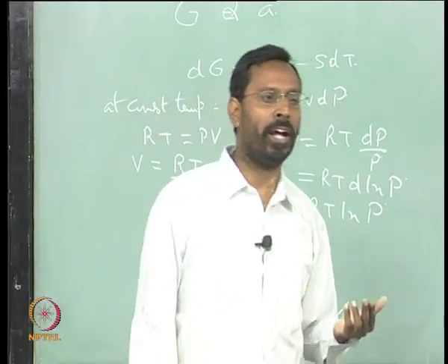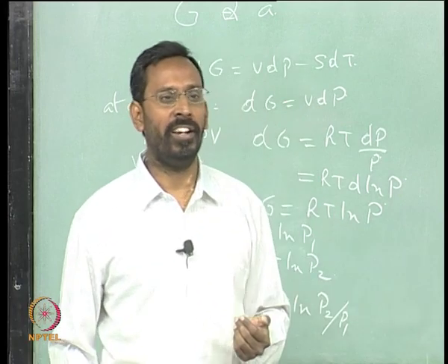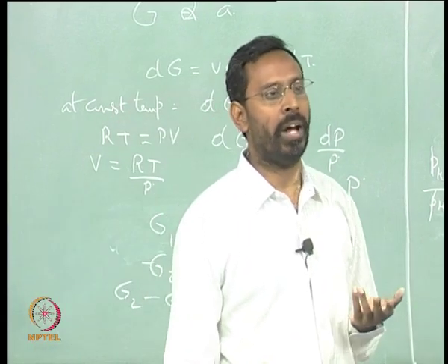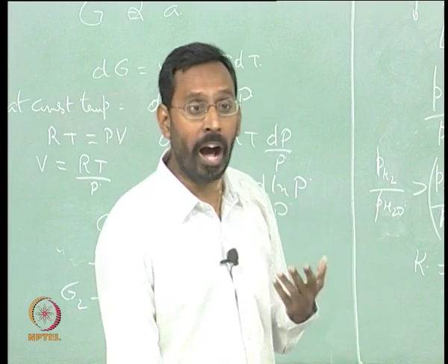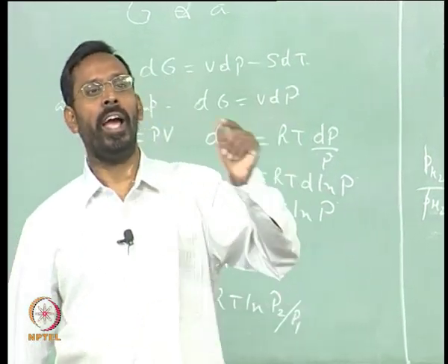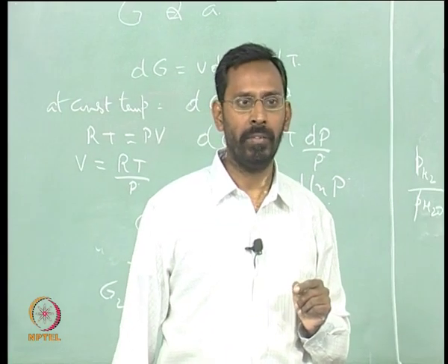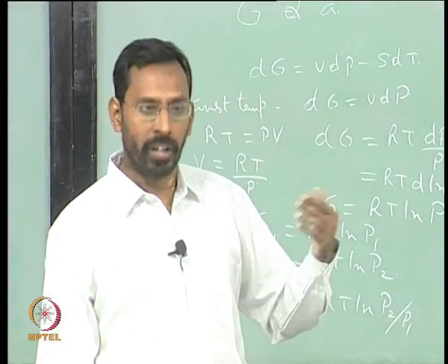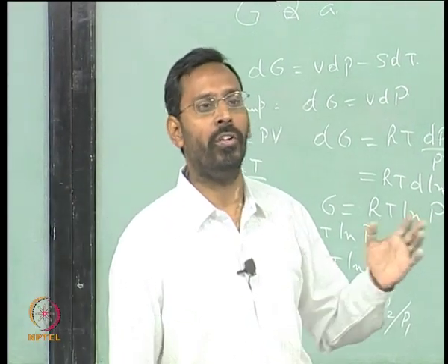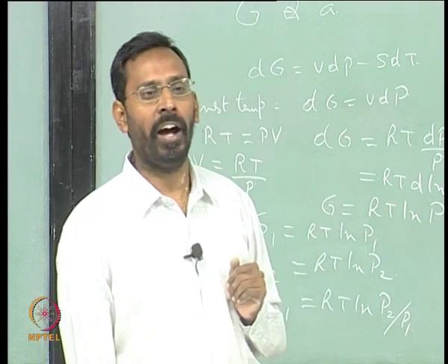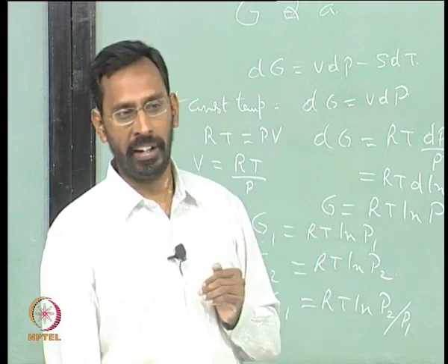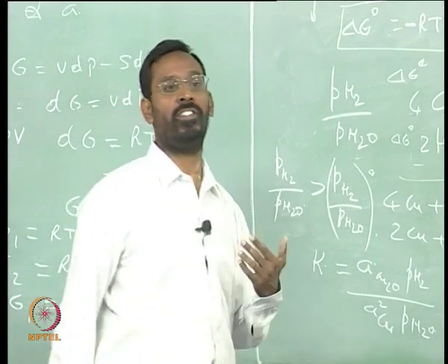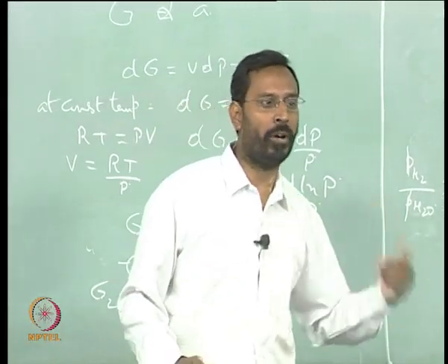Of course, luckily for a plain carbon steel, we are talking of a mild steel, let us say it is about 0.2% carbon. So, it can more or less be treated as a pure iron. So, activity of iron actually is 0.9998. If you are considering steel containing 0.2% carbon, the activity of carbon is accordingly the value 0.0002, and activity of iron will be 0.9998 if it is a binary alloy. So, if it is a multi component alloy, if it is a stainless steel that I am talking about, then accordingly I have to consider what is the activity of each.